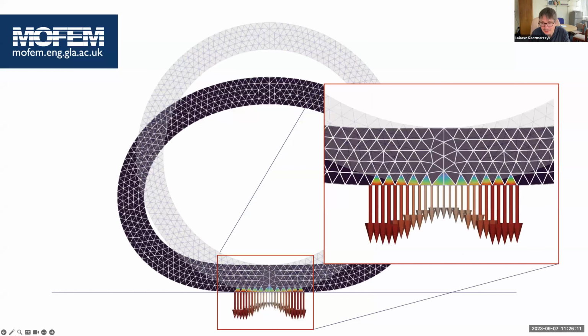Nevertheless, I will show you how that looks. Inside of those triangles you can see the approximation of the Lagrange multipliers in HD space, and the trace of those Lagrange multipliers generates the traction. Okay, so when I have this cylinder pushing against the rigid plane, I have a contact, and those Lagrange multipliers generate the traction.